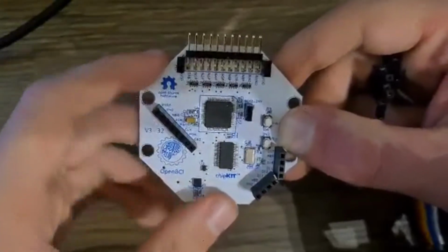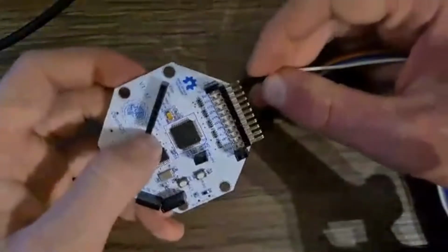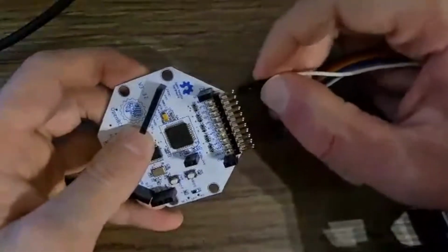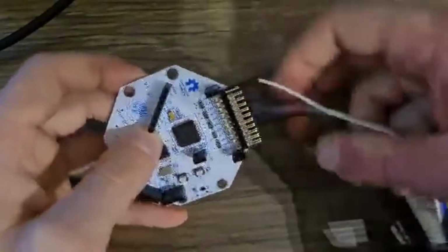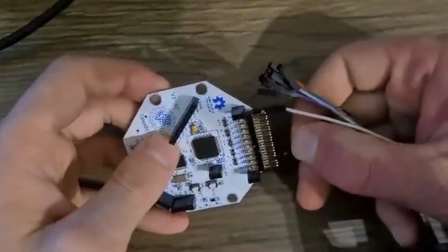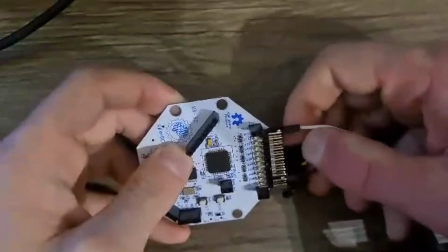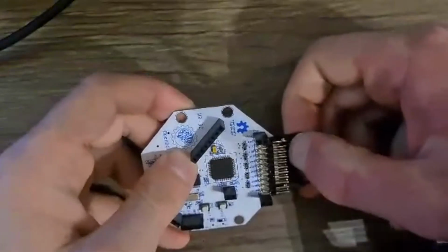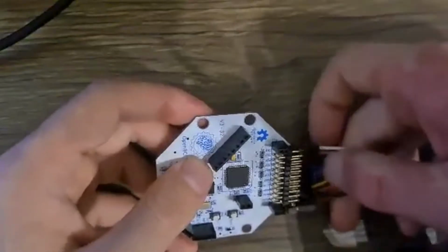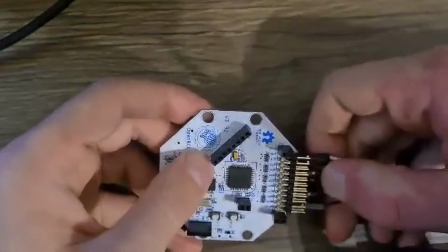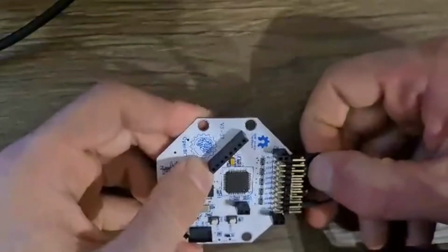So for this example here, this one is going to be our reference electrode, which we plug into here, and this black one is going to be our ground electrode, which we plug into bias, and then the rest of it. The OpenBCI GUI has a color-coded channel system, which usually corresponds to the wires that you have over here, but you can use any color for any channel. It doesn't really matter. It's just helpful when you're using the GUI. So just plug all your wires in.